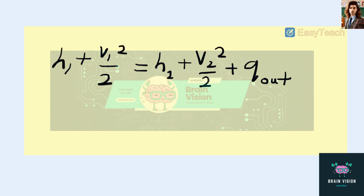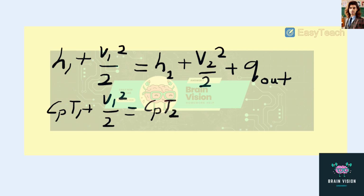And what we can do is rewrite enthalpy in terms of the constant pressure specific heat capacity and also temperature. So we can see that H1 is equal to Cp T1, and V1 squared over 2 is equal to Cp T2 plus V2 squared over 2 plus Q out.